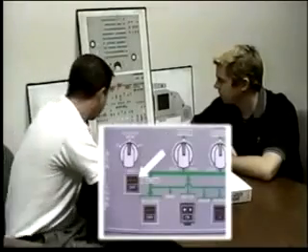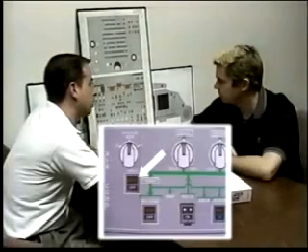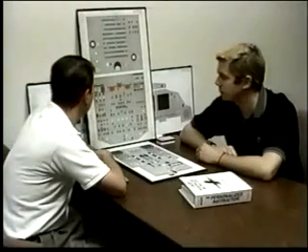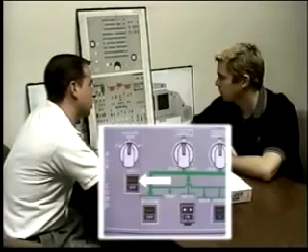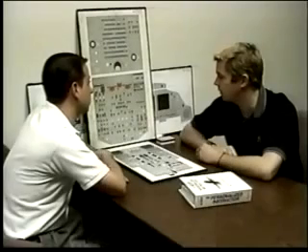Pack 1. With the system on, when would the pack flow valve open? When there's sufficient bleed air to open the valve. What about fault light on pack 1? Fault light on pack 1 indicates that there is an over temperature or a valve disagreement.